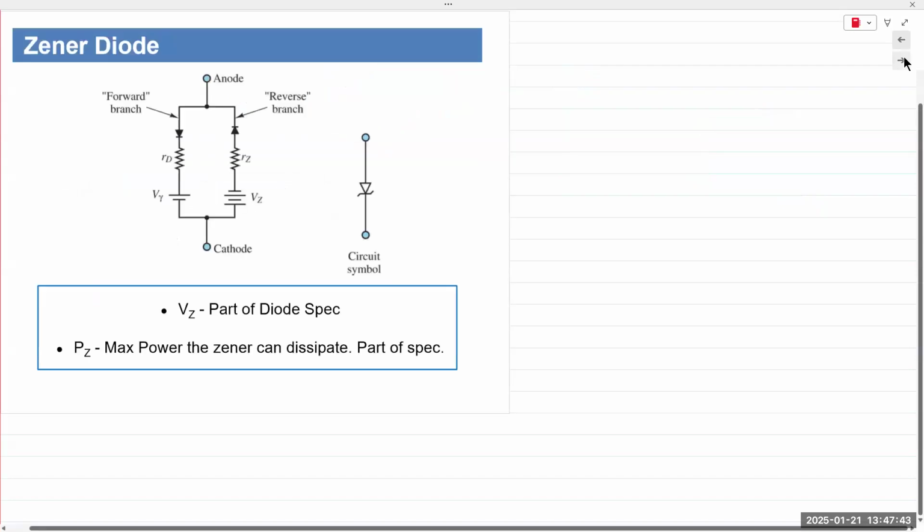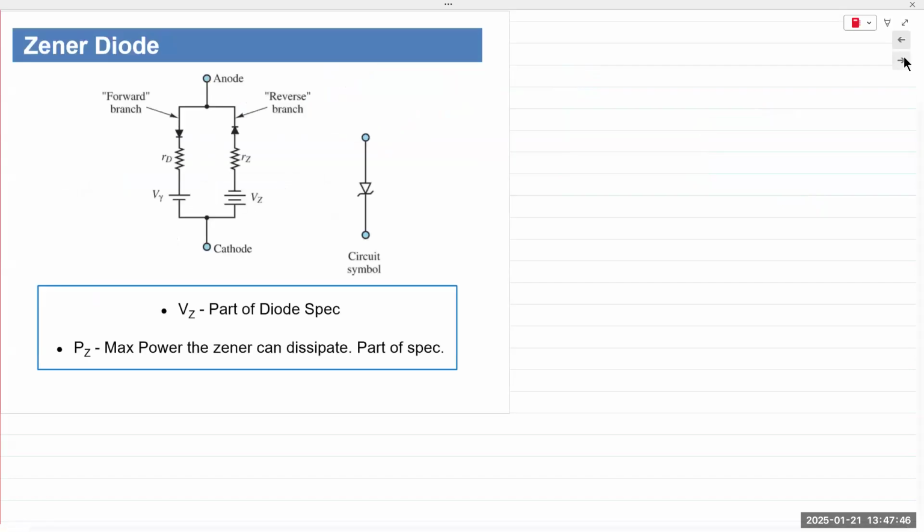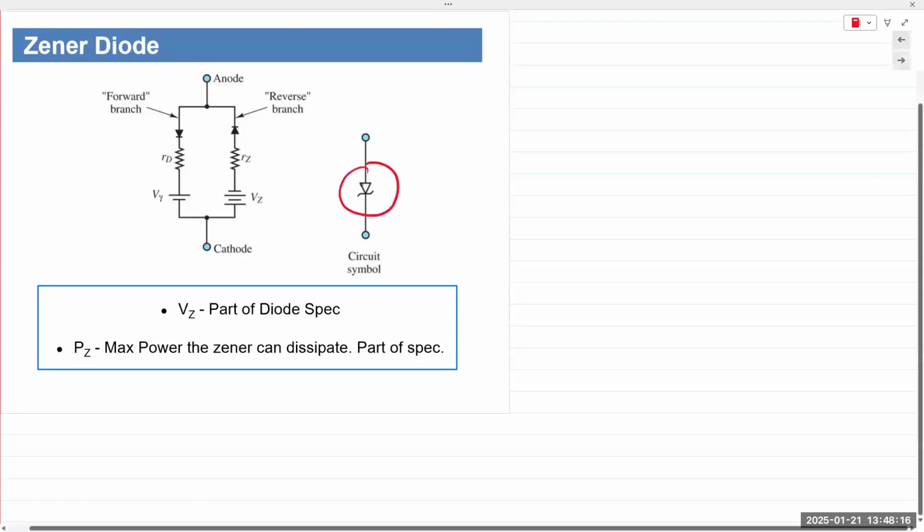Regulator circuits, again, depending on the application, especially modern devices like your charger adapters or your smartphones, smart devices, laptops, computers, require very well designed regulator circuits. The simplest one of those is a Zener diode. Just by itself it can function as a regulator. So here is the symbol for a Zener diode. It operates exclusively in the reverse bias.